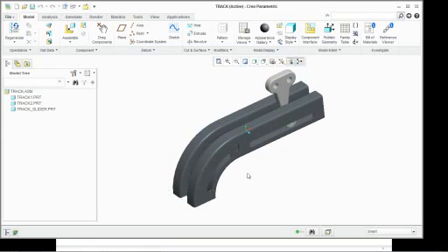I've got this track slider that runs along a track, and I've got several different sliders that we use in our company, and we're constantly making new designs out of the existing parts. Well, if this is something I'm going to be reconfiguring often, instead of changing once and forgetting about it, if I'm going to switch back and forth, I'm actually going to go in and create an interchange assembly.